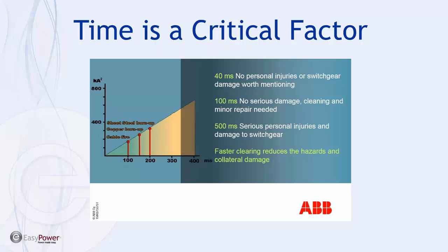So, like we talked about before, most conventional relays are going to put you at 100 milliseconds or over. With the REA arc flash and Relion, the peak-to-peak measurement mode, now we can start approaching that 40 milliseconds, maybe just being a little bit above it. So you can see that even just an order of magnitude of 100 milliseconds can make a big difference with arc flash, especially depending on the magnitude of fault current and the clearing times.